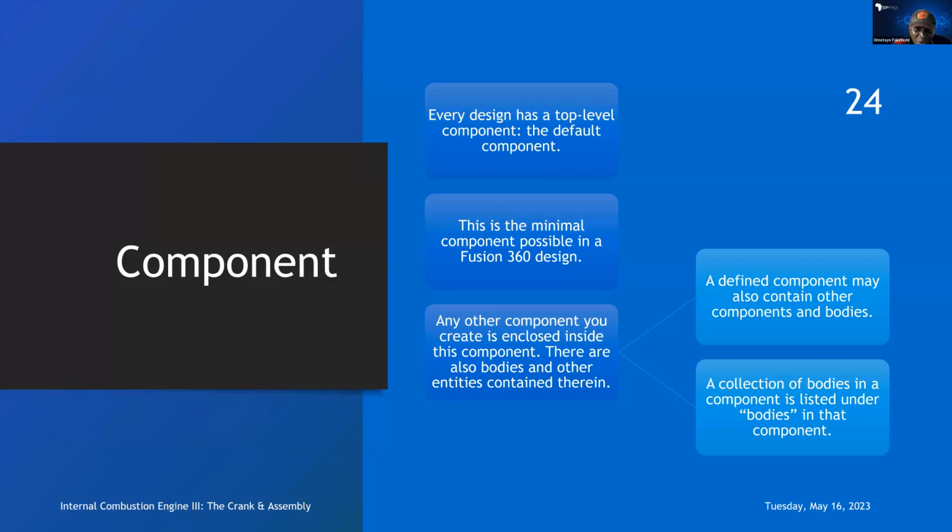So a component can consist of several bodies, but you will see that a component contains more than that. A component is the closest idealization of what you call a part, a part of an assembly. But a component is a specific definition abstractly, and you need to bear that in mind when you are working with assemblies and designs in Fusion 360.